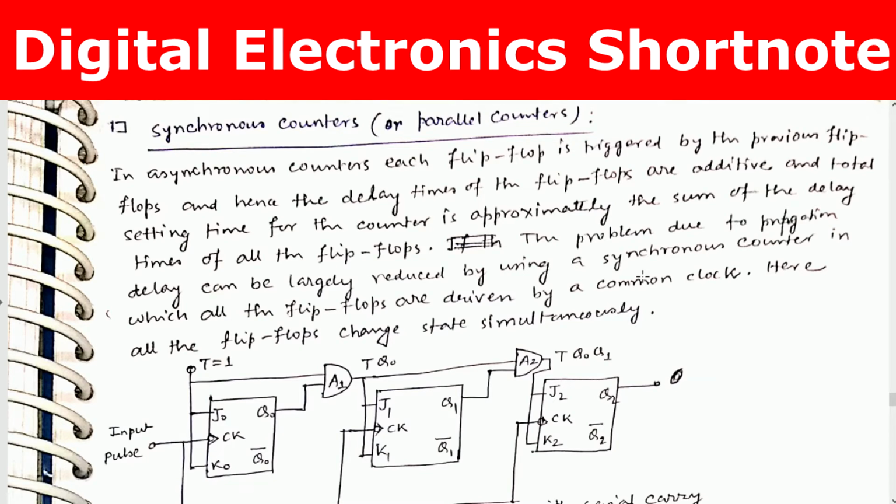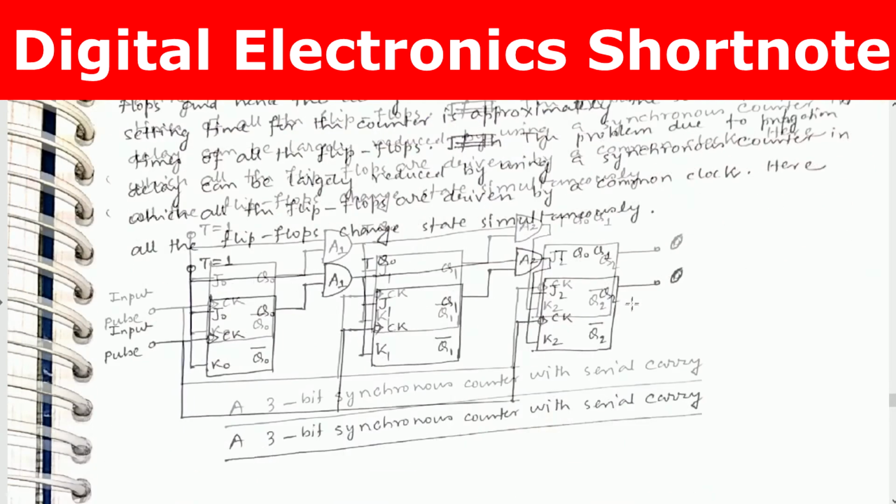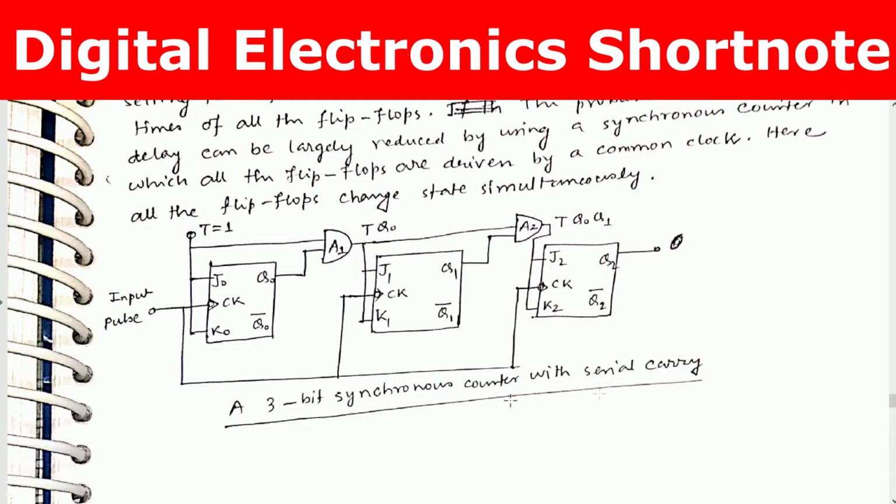Synchronous counter or parallel counter. In asynchronous counters, each flip-flop is triggered by the previous flip-flop, and hence the delay times of the flip-flops are additive, and total settling time for the counter is approximately the sum of the delay times of all the flip-flops. The problem due to propagation delay can be largely reduced by using a synchronous counter in which all the flip-flops are driven by a common clock. Here all the flip-flops change state simultaneously. This is a 3-bit synchronous counter with serial carry.